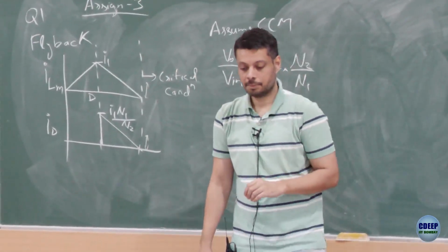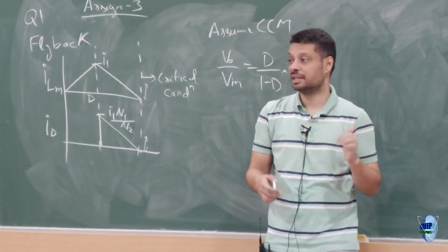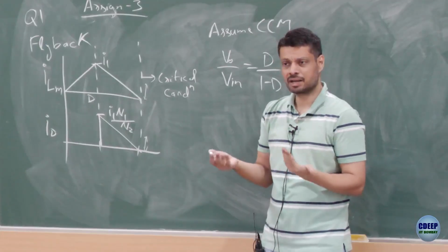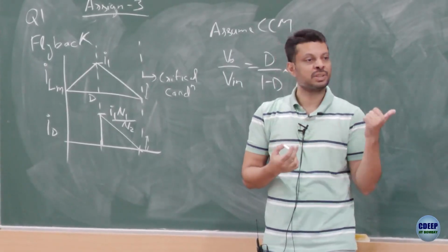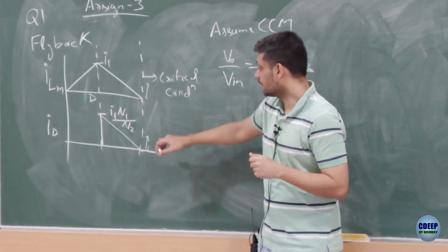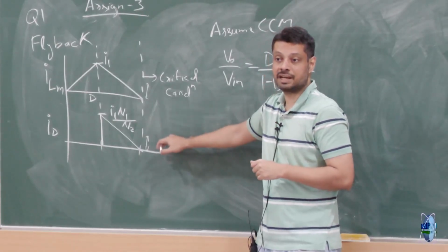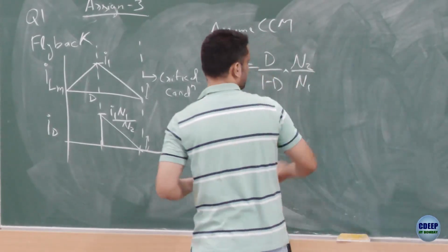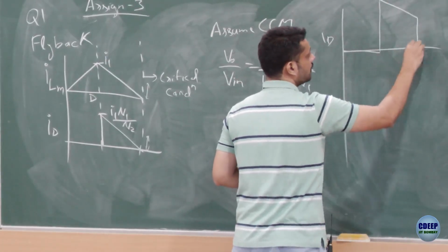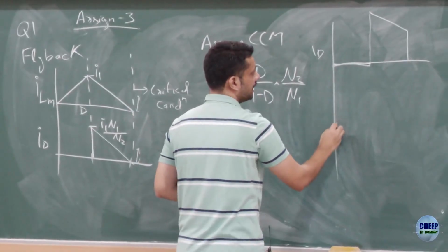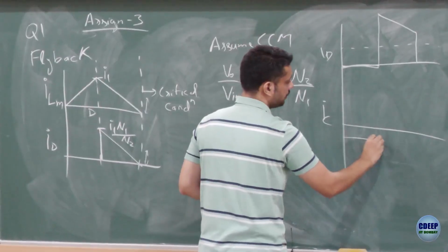Okay. Part C, the output voltage ripple. Again, we have not derived the output voltage ripple for the flyback; we derived it for the buck converter, and probably the boost also as part of the assignment. Can you do this one? You know the diode current, a shifted version of this, right? If you subtract the average, you will know the capacitor current. So if this is the diode current, you subtract the average value, and you will get the capacitor current.